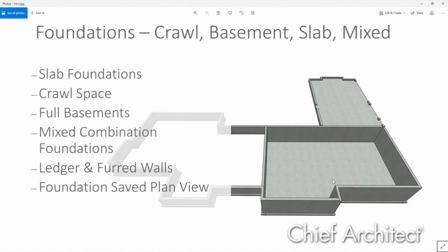Great, thanks. Hey, so on the foundations, I have a question, and I also wrote that in, but the pre-questions had just limited area to type my question in, so I kind of abbreviated it. The question is, in this part of the country I generally do slab on grade, which has beams, like a waffle slab would be my best example. So perimeter beams are 12 inches by 36 inches, plus or minus. And then there are interior beams of similar size, and then there's like a 5-inch slab.